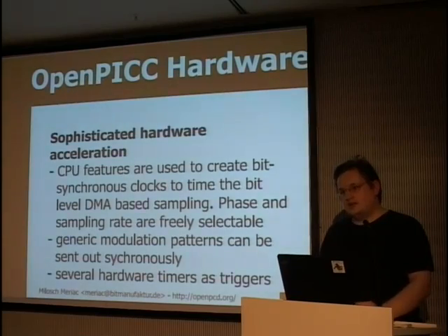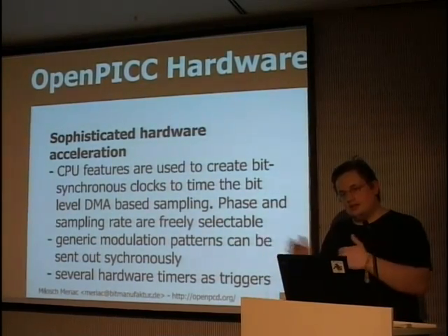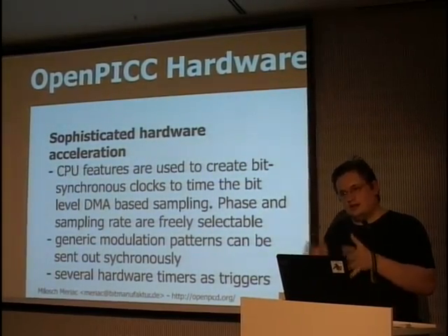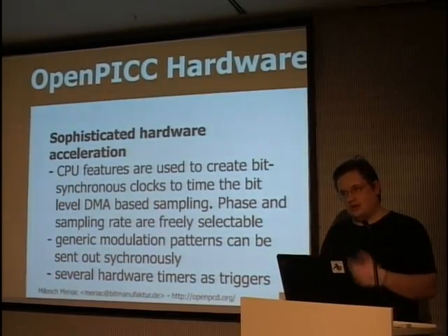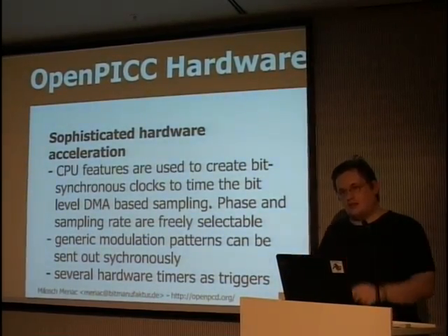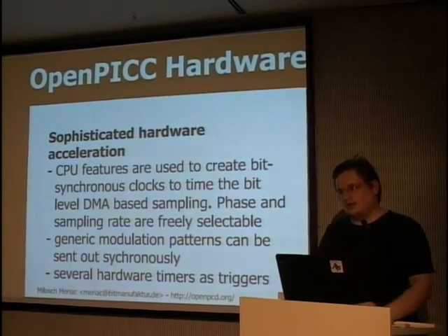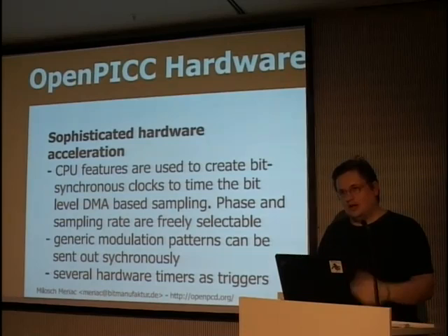There are reconfigurable timers that make sure that the timing constraints are managed, so you don't have to do a silly synchronous design, but you can do a really intelligent reader design where you don't have to poll constantly, but you set up stuff correctly, and most of the work is meant to be solved in hardware, so you can do your stuff in software without having to know much about real-time programming.